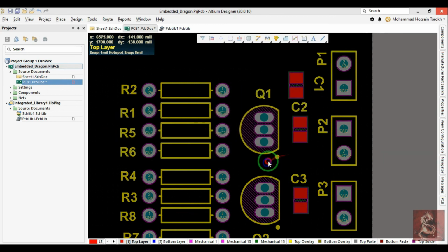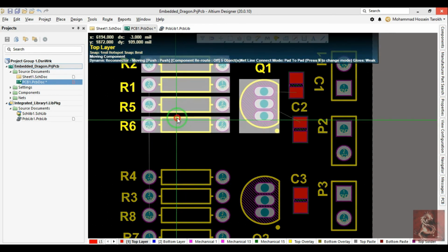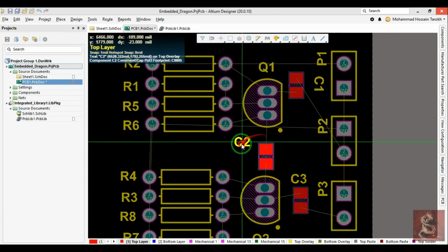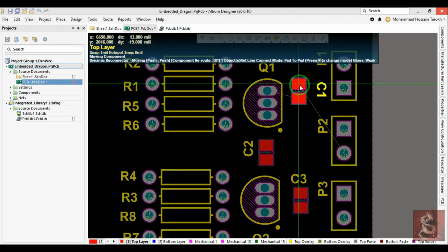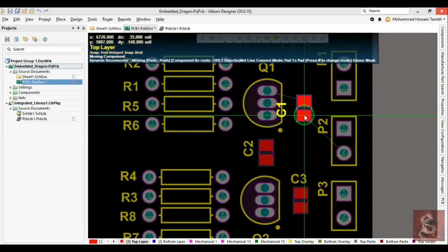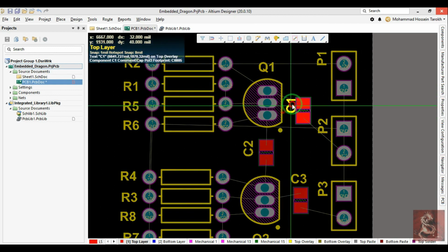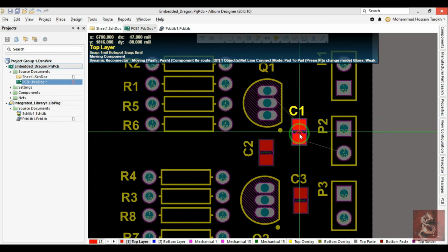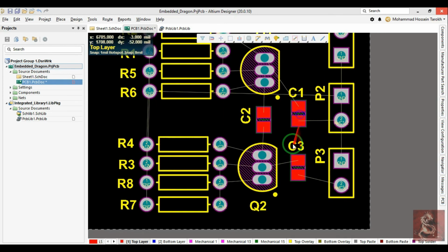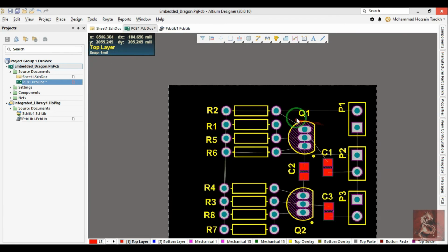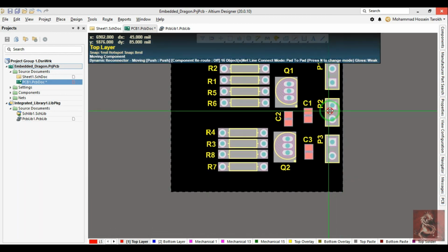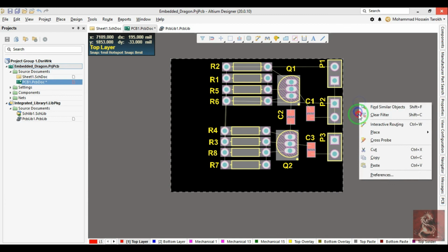So we move these components a little up. It's this one here in between. It's a good start because we have SMD and through hole components at the same time. So I bring it here in front of the connector. In this case it's not very important, and we still see that we have space, so we save space.